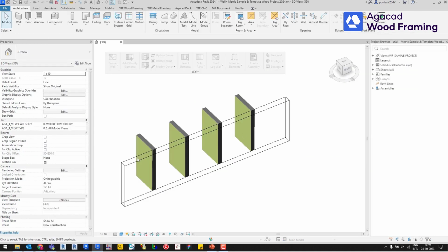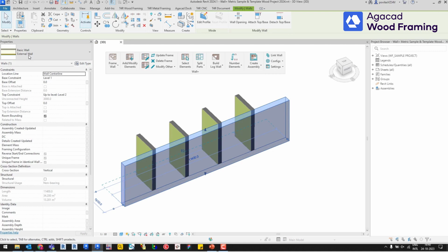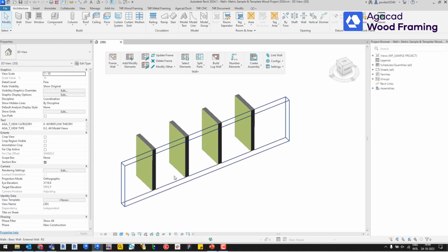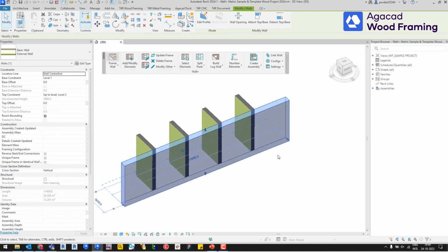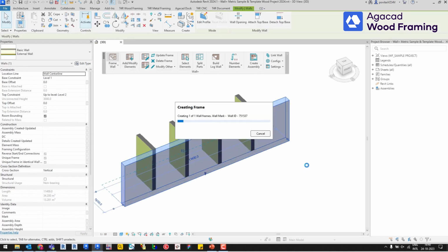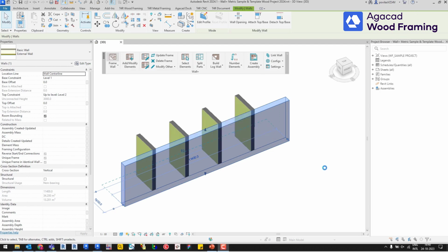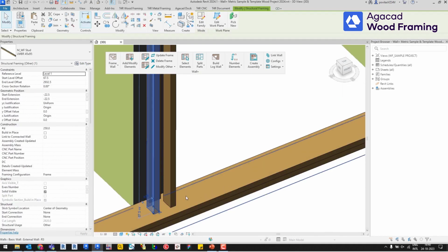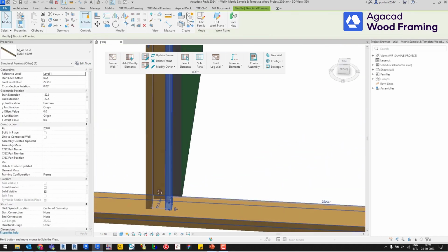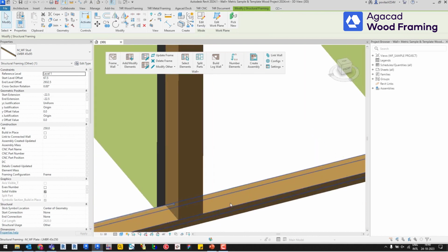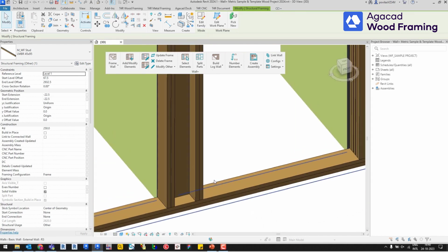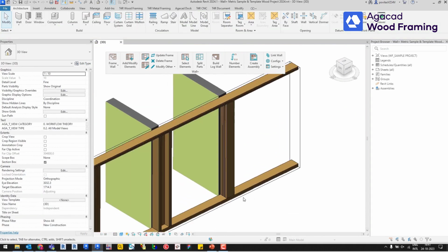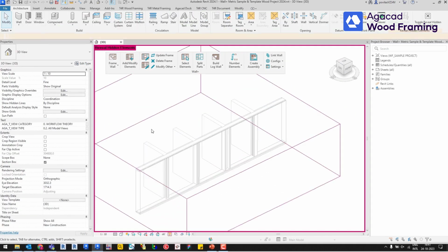Okay, and there's my main wall right over here. Let's call it external wall, and 4 internal walls, type 1 to 4, that are connecting to my external wall. So if I go and frame the external wall, I will get these 4 distinct and unique T connections as I described in the configurations, obviously. So wall type 2, for example, will create this kind of configuration. Wall type 3 will create this kind of configuration when joining another wall and creating a T connection, right?